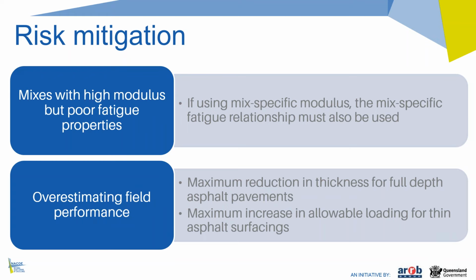The third major risk identified relates to increasing the mix modulus, but at the detriment of fatigue performance. Mixes with WRAP have certainly been found to fall into that category. Hence, the technical note requires that when the mix-specific modulus is used, the mix-specific fatigue relationship must also be used, and vice versa. It's not a case of picking and choosing one or the other. They both need to be used together.